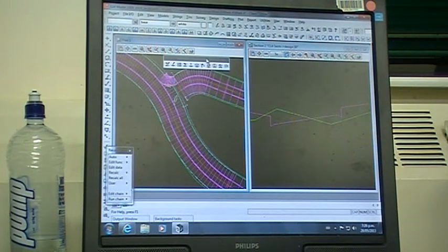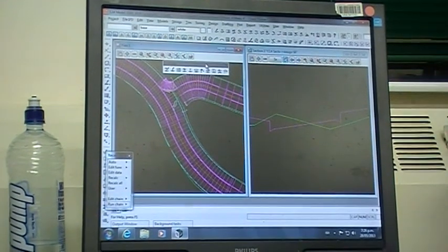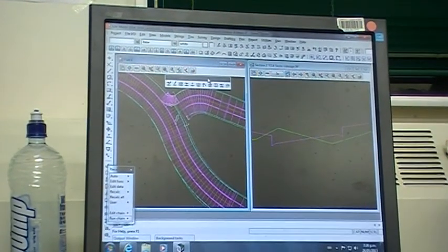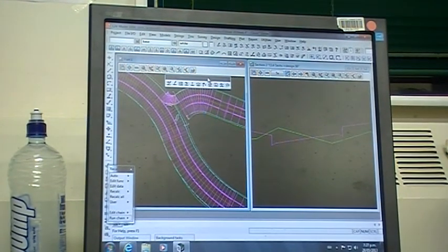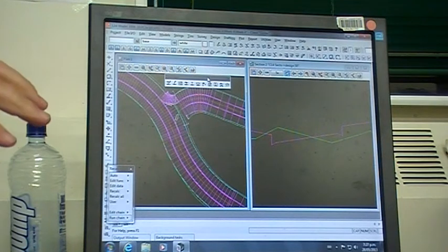Okay, which is irrelevant to you, but what it was is there was a performer within a technical publication that used different steps so that instead of just on a large job having one big blanket assumption for the coefficient of pervious and impervious areas, it allows us to be a bit more flexible and talk about percentages of area that are paved and areas that are long grass and areas that are rocked.